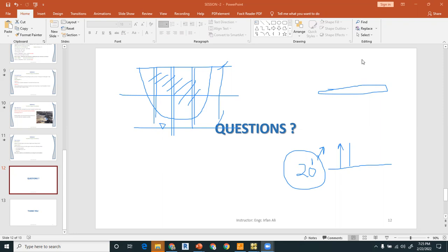I was talking about the pressure bulb, that if you calculate the pressure bulb for your structure, for example, if you have 2 or 3 story buildings, this 20 feet thumb rule is enough. For example, if you have a 3-story commercial building and the water table is below 20 feet, then you are on the safe side.